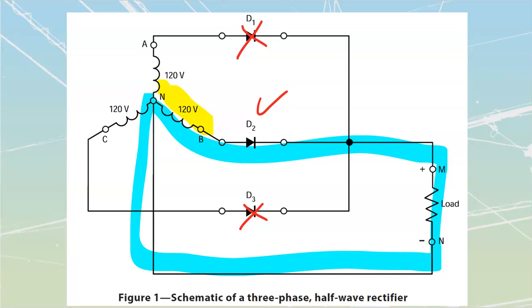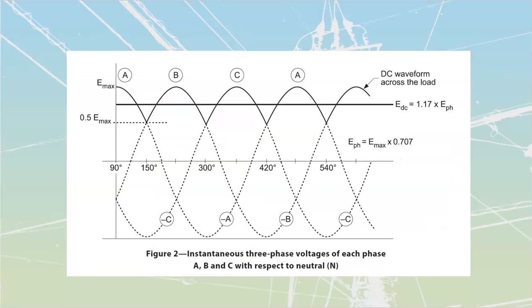So, going into what we'll cover over here, we're going to start changing these. In some cases, we will just use diodes to rectify into DC, and then we'll chop that DC up. In other cases, we're going to use SCRs to adjust it into variable DC. Either way, no matter how we create it, whether it's half wave or three phase, we're going to have two things in common.